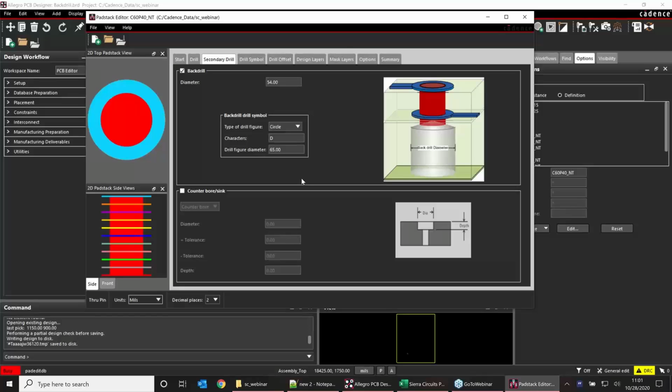Less than 1 gigahertz is not considered high frequency, because our manufacturing technologies, our material technologies, and our modeling technologies all have basically progressed quite a lot. And therefore, we are able to manufacture more precise signal traces and have more control over material properties than we used to have 30 years back, 20 years back.